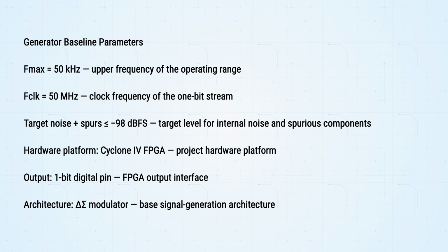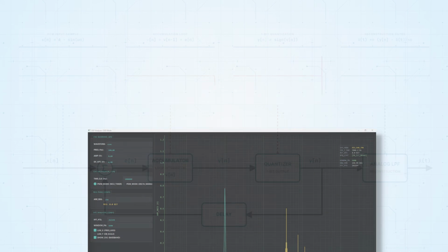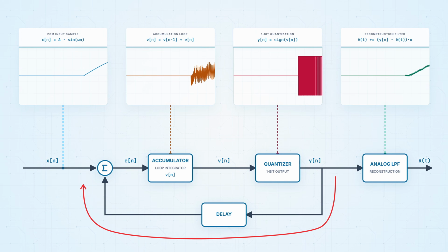In the previous episode, we clearly demonstrated that a traditional PWM creates powerful spectral components at the carrier frequency, its harmonics, and its sidebands. These high-energy components have to be heavily suppressed by an analog filter, and doing that is not always an easy task. A delta sigma modulator works very differently. It has memory and is controlled through a negative feedback loop.